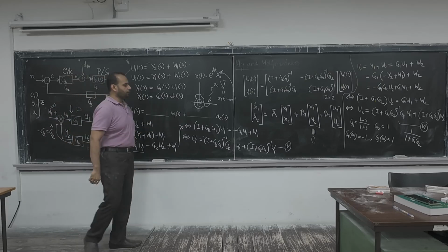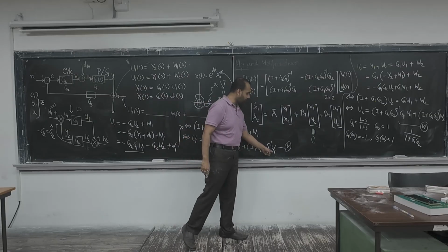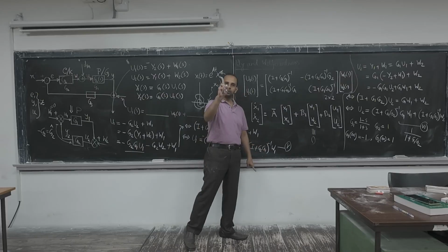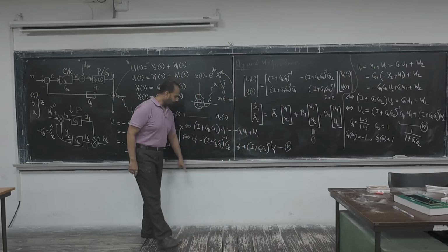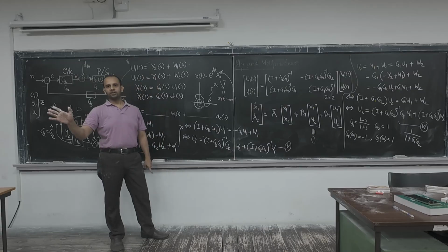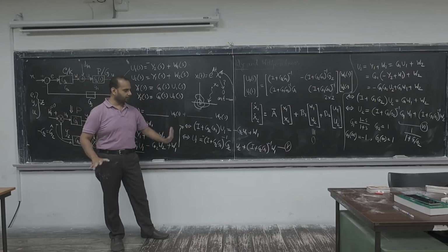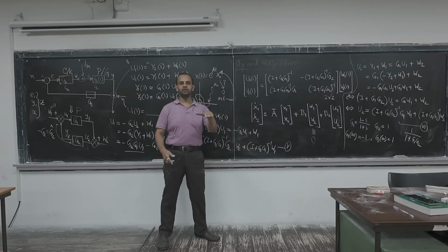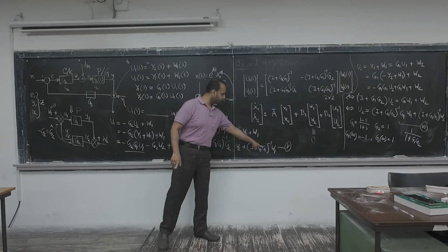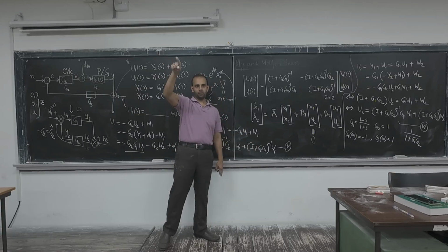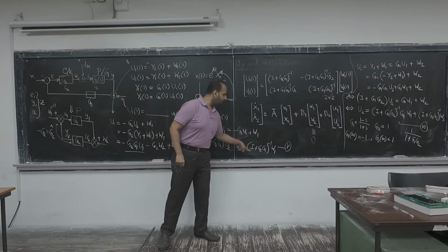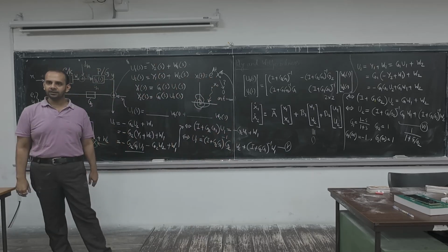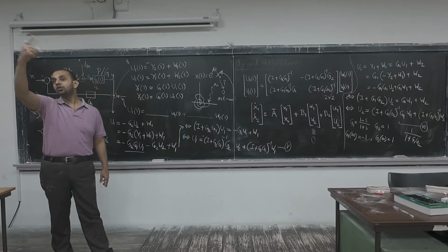Like, if I use a value, for example this W1, that is a reference signal. Suppose this is R and we are going for a unit step, so this will always be one, right? And suppose there is no disturbance W, so this part is completely 0, so now Q1 will be this one. Now you see there is a unit step, there shouldn't be any problem, but all of a sudden when it goes to very high frequency, or theoretically at infinity, it explodes. But that is not a real phenomenon, right? An asymptotically stable system, if everything goes fine, should not explode.